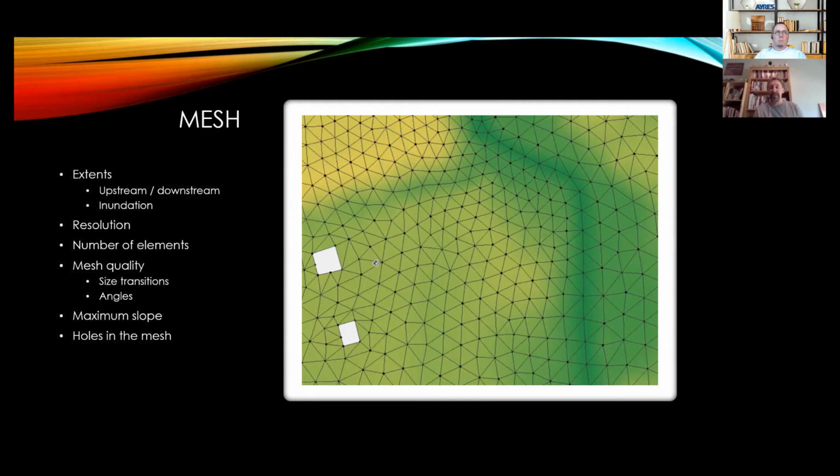So what that means is, if you're not familiar with that, either the mesh is too tight or the time step is too large, or it might be a combination. What that results in is elements in the model getting skipped, which can result in a bad run, and it can definitely result in instabilities.